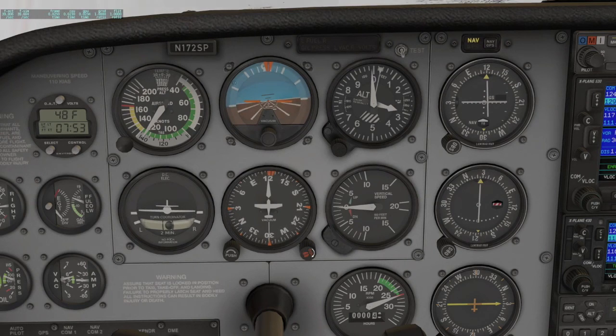Few adjustments. We're getting close, I believe, to the VOR, and the closer we are to the VOR, the more sensitive it becomes, because the angles or the distances between the radials become small. Okay, good. So now we're almost over the VOR, so it's going to switch.